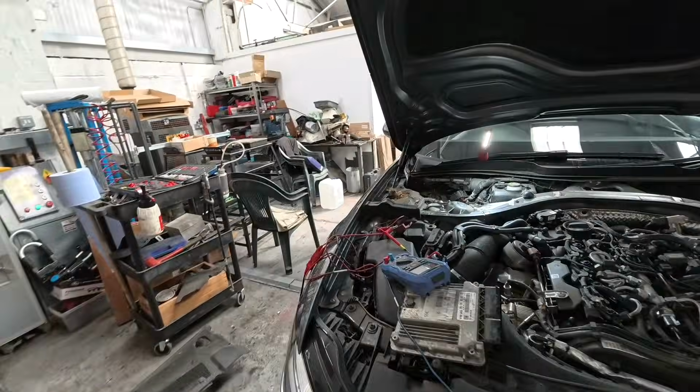Now, as some of you probably saw on the scope trace, we're getting no pulse width modulated signal. We could see that the control wire is being grounded, and so it comes from the ECU. So the only other potential that we have there is perhaps a shorted ground control wire between the engine ECU and the solenoid valve. So I've taken a liberty, because I like to take liberties.